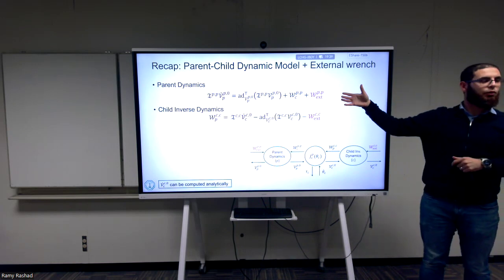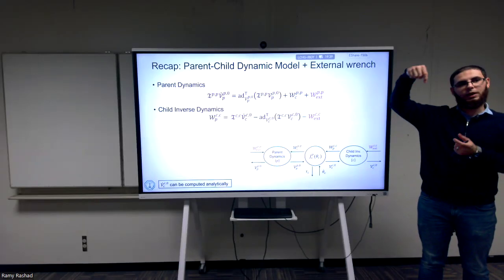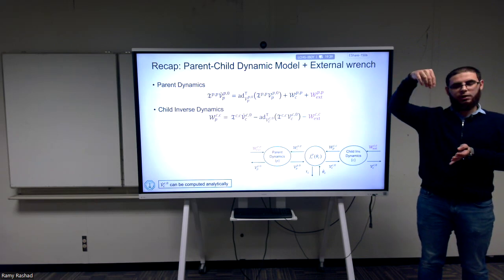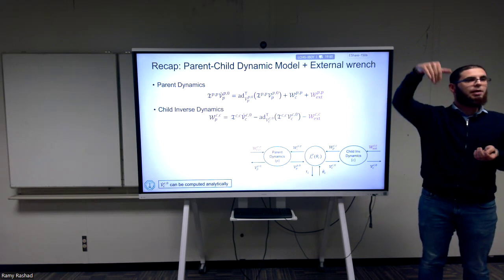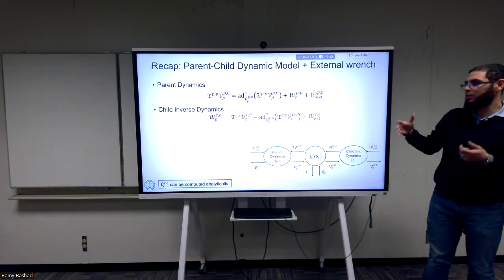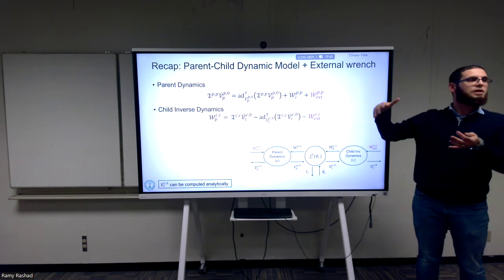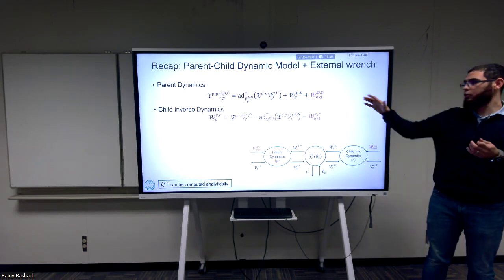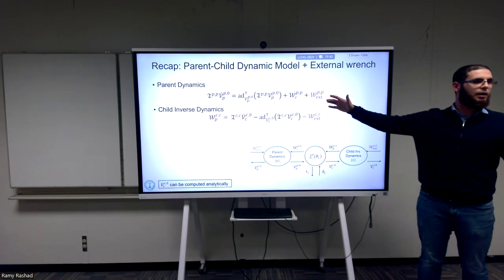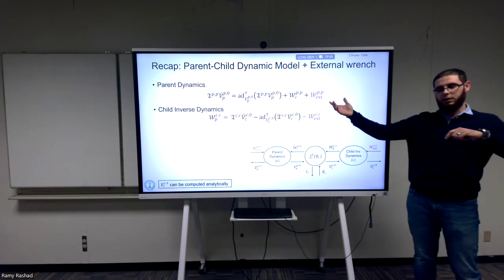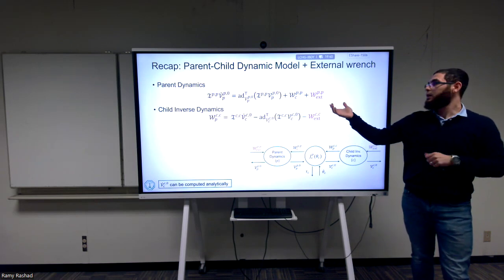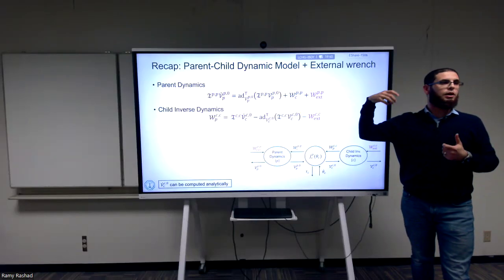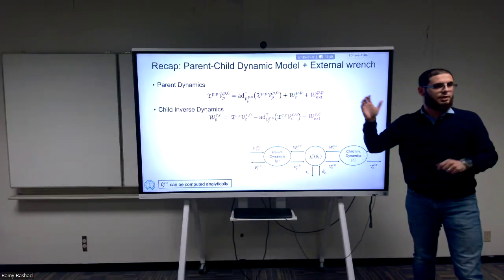This is also how you can include gravity. So you can assume that the gravity is something at the center of mass and it's pointing downwards with respect to the Earth frame, and then depending on how you choose the stationary frame, you can represent the gravity there, and you can transform it and write the wrench in terms of gravity this way. So this is a general way of how you can also include aerodynamics. If you have, for example, a drone or an omnidirectional or a fully actuated multi-rotor aerial vehicle, then you can also have the external wrenches due to the thrust, due to the propellers acting in the same way, and so on.